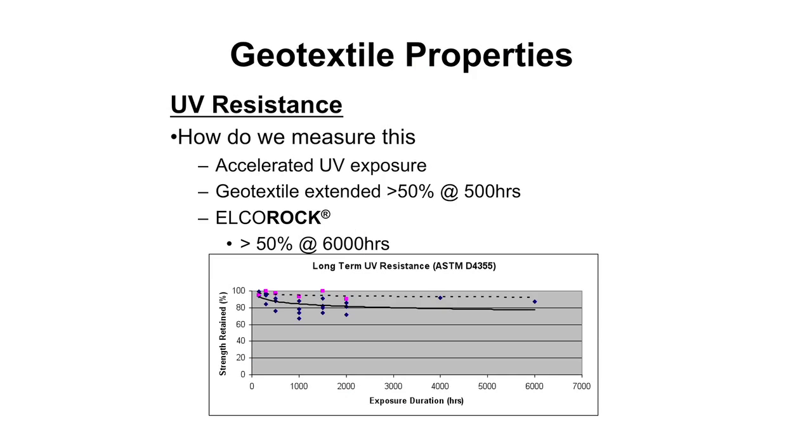Okay, the next one is UV resistance. And what we've got to bear in mind is geotextiles were developed initially to be buried as filtration medium in subsoil drains and so on. So the whole concept of geotextiles was developed around the concept that you'd bury it within 2 weeks of it being exposed. What we're doing with these geotextiles is a long way away from what the traditional use of geotextiles were. So we've had to rethink the way we've developed the geotextiles in terms of the specifications of the polymers.